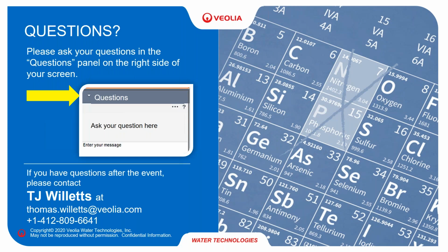I consider a sweet spot for BioP when I have high CODs, let's say over 2,000 milligrams per liter, and also high phosphorus, so I'm coming in at about 50 to 100 milligrams per liter, and I know I need to meet a discharge of 1 to 2 milligrams per liter, and maybe even lower than that.